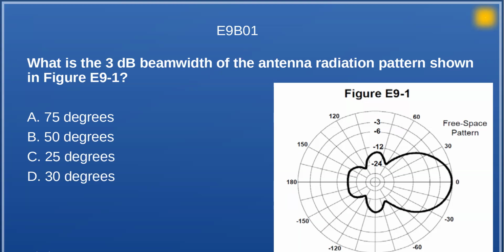You measure it from the lower and upper 3 dB half power points. They call them cutoffs. Same thing for this. Once you get at an angle beyond that, you're less than half power. And that's just a standard for measuring a lot of things, the half power points.